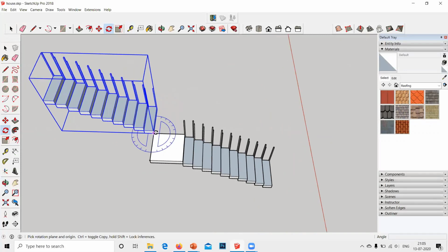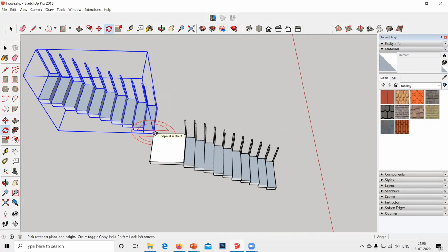Select this endpoint. Okay, make sure you have drawn this portion, whatever you call this. Again, we call it D. It is on the blue axis. As you can see, to make it blue, you have to enter your upward arrow key. You have to delete again. You have locked your plane.